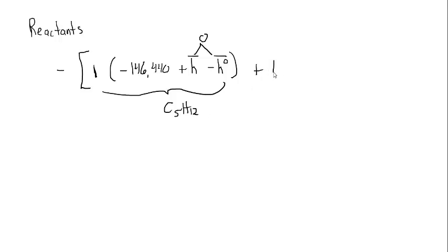And then you would have 12 moles total of oxygen, right? Because it's 1.5 times the stoichiometric. Enthalpy of formation of oxygen is 0. The difference between the sensible enthalpy at 25C and the reference state enthalpy at 25C is also 0. So oxygen 0, and same thing for nitrogen.